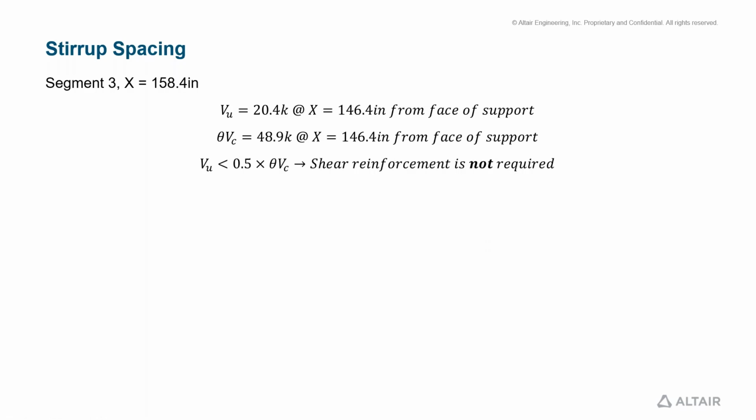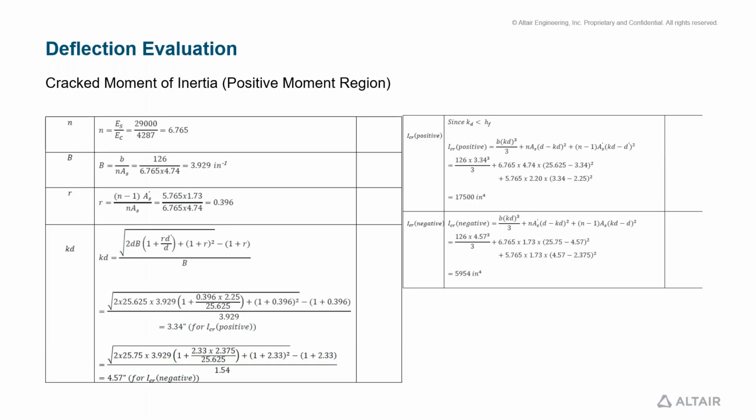Now for segment 3 here, we've actually found that shear reinforcement isn't required based off of the demand versus capacity relationship that we see here. So we can move on to deflection evaluation.